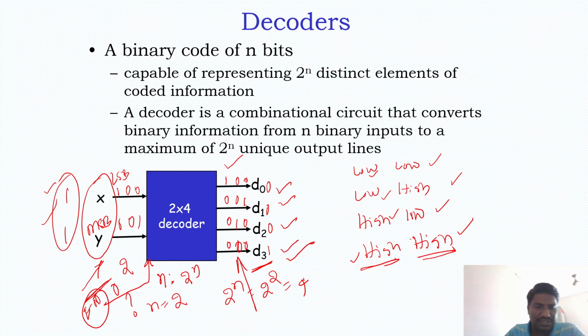So this is a decoder without enable; you can also build a decoder with enable. This enable will allow us to cascade decoders to get higher order decoders. In one way it is useful; the other way it is useful is to save power. When we are not working with it, I will just make this 0. Once again, this enable can be active high or active low logic. Because I am not showing any bubble over here, it is active high logic. That means if the input is 1, the decoder works. If the input is 0, the decoder is not going to work; it gets disabled.